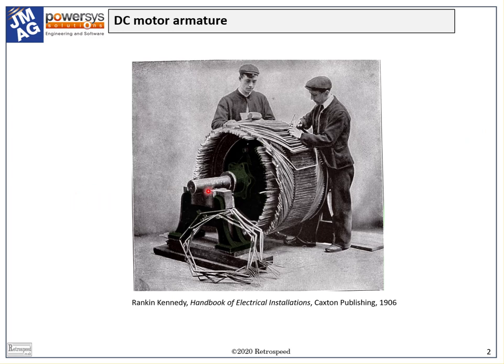Here is a photo more than 100 years old showing the manufacture of the rotor of a fairly large DC motor. The power windings are on the rotor, also known as the armature, and this feature is nowadays seen as undesirable because, for one thing, it limits the speed and the diameter, and the rotor is difficult to cool, so it tends to run hot.